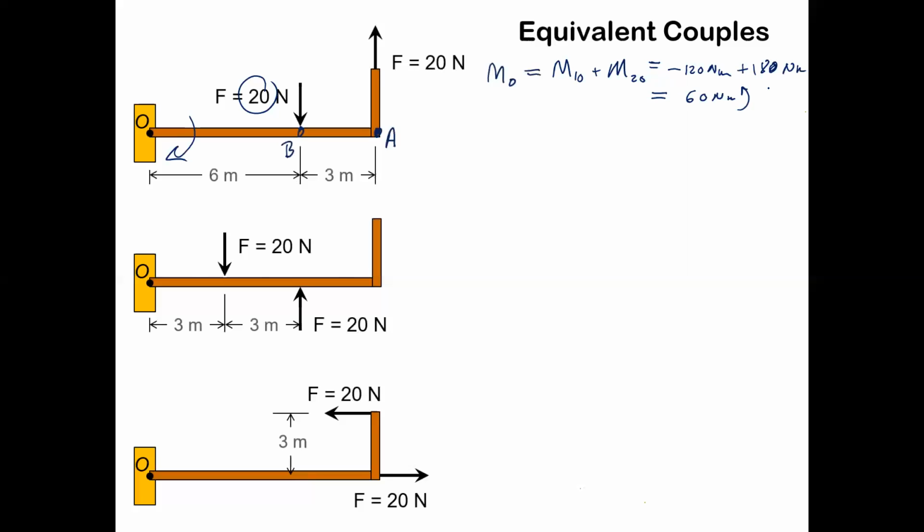Now, what about if you decide to look at point A? What's the net moment about point A? Now, we're not worrying about an axis at O. The moment about point A is going to be also M1 plus M2. We're going to call this, I guess, F1, sort of 1 of the 2. And what's the moment arm about point A for F1? The moment arm is 3, so it's going to be 20 times 3. It's going to be 60.